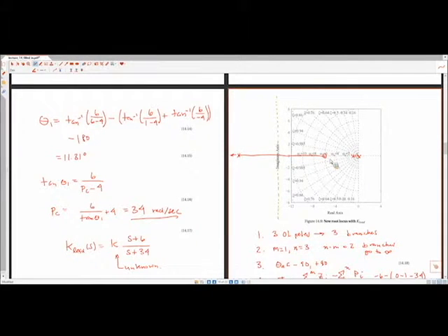Completing this is essentially matching our sketch, basically saying, what do we want ideally? So we said that we design such that the root locus directly goes to the points negative 4 plus 6i, and negative 4 minus 6i. That's a kind of waypoint. Once you do some of these design tools, you can actually say we force the root locus to go to this point. So this is not an approximation. It will directly go through the point negative 4 plus 6i. This can help you draw the root locus plot as well, because this is kind of a waypoint in between.